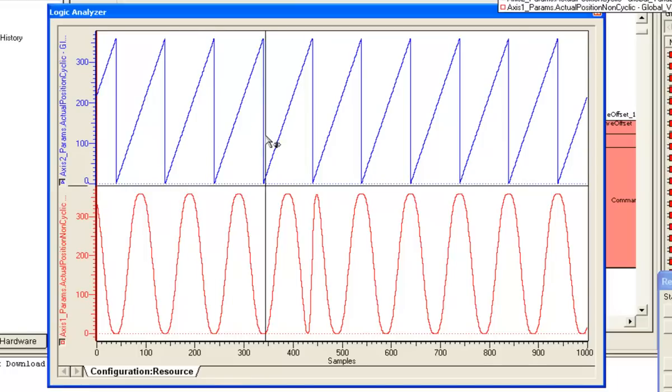And then, you see, midway through, we execute the shift, and the shift takes place over 180 degrees of the master. And post-shift, we see that the relationship between the master and slave has changed. The master, at 0, is now the 180 degree point of a slave, and so on. So this shows a nice graphical example of the effect of the shift.